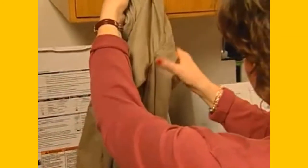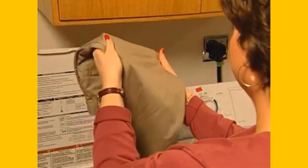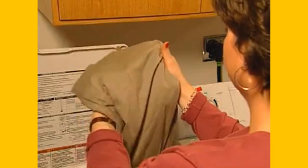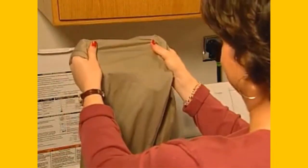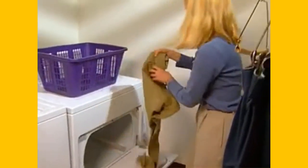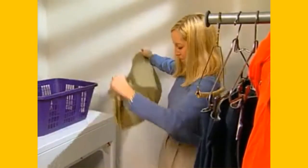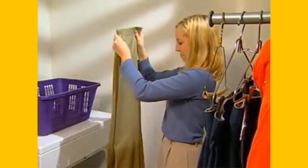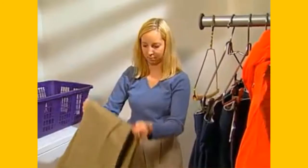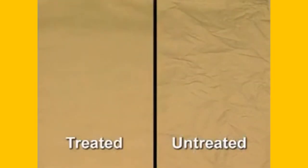Clothes that are easily soiled must be finished to both repel and release dirt and grime. Fluorochemicals can be adjusted to provide less surface tension, so that the finish releases dirt and removes soil during washing. Contemporary lifestyle dictates that we look neat while we work hard and play hard. So fabrics can be treated to resist wrinkling, to retain a smooth appearance, keep creases and pleats in place, even after laundering. Currently, the most popular chemistry used to resist wrinkling is resin-based.